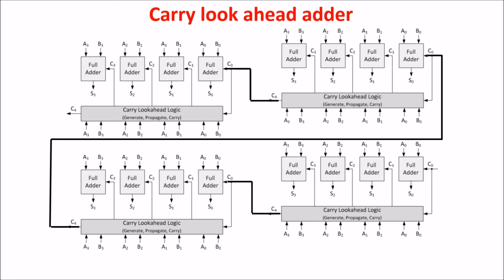So there is a trade-off to reach, for example considering blocks of 4 bits connected together. In this way, we keep the maximum number of inputs of a gate at 5, and the total delay is 4 T-gate times 4, so 16 T-gate, which is less than the 33 T-gate of the ripple carry adder.